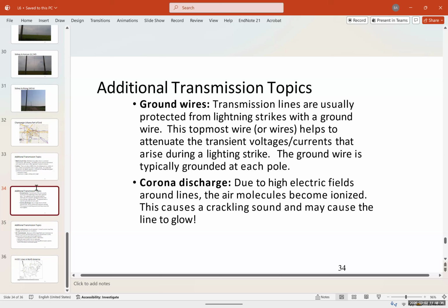So if there is a smoking smell or very bad smell in the car, leave it in the car for 10 minutes. Its main purpose is oxidation. When ozone comes in contact with anything, it's going to oxidize it, and it's going to neutralize any smell that it has. It's dangerous for humans if you inhale it for long term, and after 30-40 minutes, it's going to turn back to oxygen.